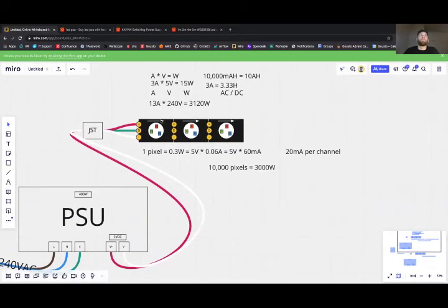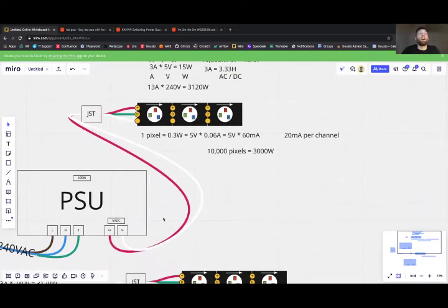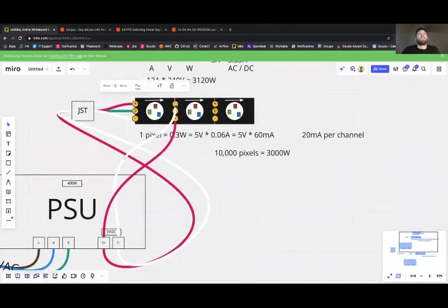We use power injection. So it just so happens that, as we discussed, since these circuits are in parallel, it's completely fine to add additional wires that connect in at any point here. So you can complete this circuit again at any point, wherever you want. So typically this means figuring out the length over which voltage drop will occur and adding your wires in there.